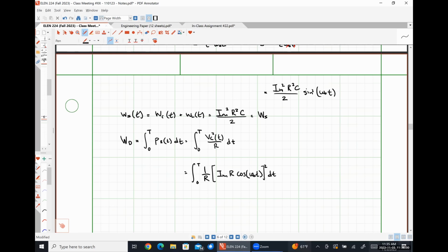All right, so again, using my circuits one trig identities and all that kind of stuff. When I square this cosine term, I'm going to get a factor of 1/2 and all that kind of jazz. The integral over the cosine of twice omega t part is going to go to 0 because I'm integrating over an integer number of periods. And so what I get left with